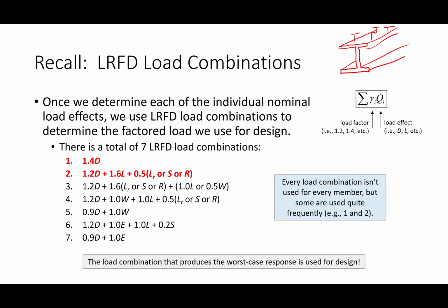And that's what I mean when I say staged construction. And it is possible that if you think of things in terms of performance ratios, that the beam actually sees its worst conditions during construction, okay? That's actually the worst state of stress, the worst design condition is during construction. That once you get the concrete deck on there and that it cures, the bridge is fine. A good example of where that might happen is, how many of you, did y'all ever get a chance to go see that I-64 bridge in Nitro? The big one, you know what I mean? The one that they recently poured.